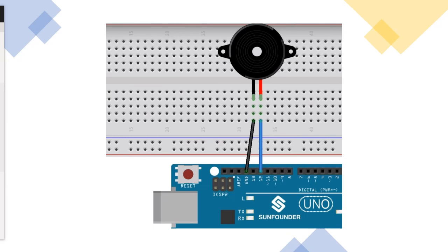We are very conversant with high for turning the actuators on. Any output device can be turned on by putting high, and turned off by putting low, as digitalWrite LOW and digitalWrite HIGH. So those are the major ways you can turn these modules, gadgets or devices, basically the actuators, on and off.